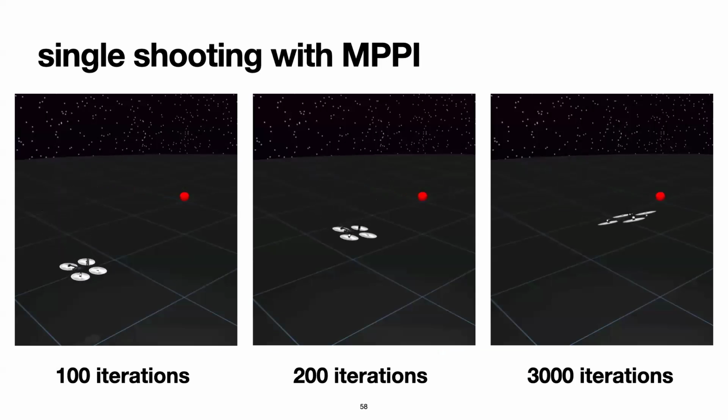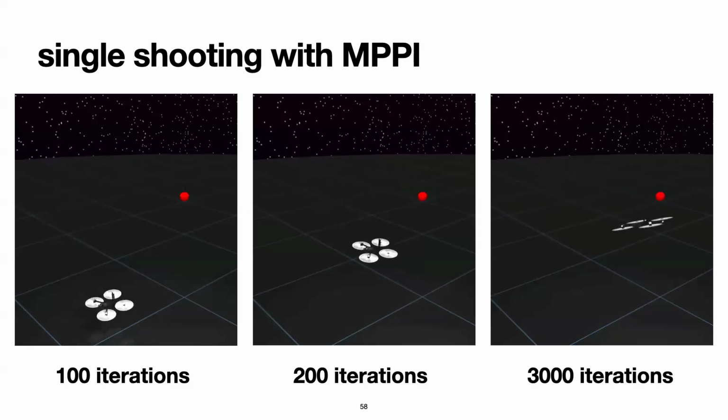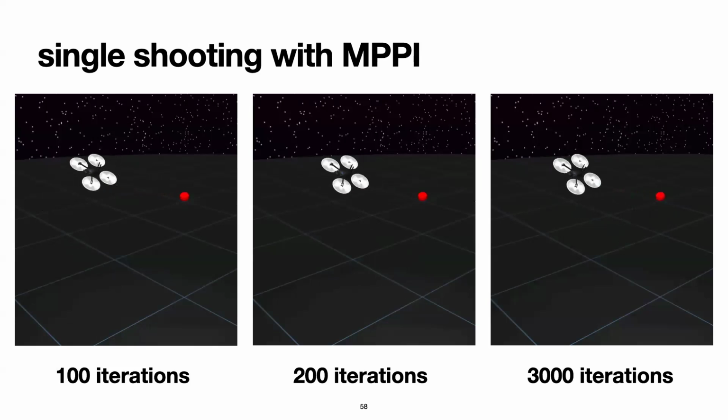But there's a hang up with this. So let's take a very simple example, which is a quadrotor that is being controlled at the rotor velocity level. So I effectively have 4 points of force control. And this is an open loop unstable system. I need clever control to keep the quadrotor flying. Otherwise, it'll just flip over and do weird stuff.